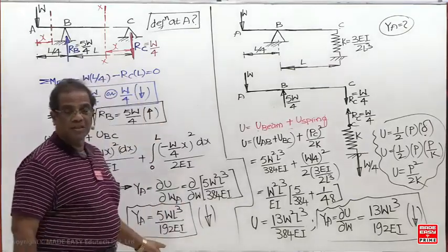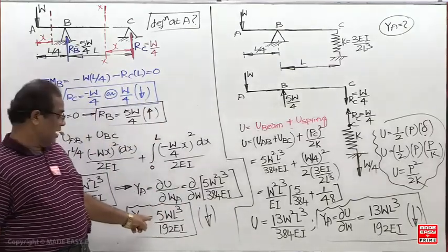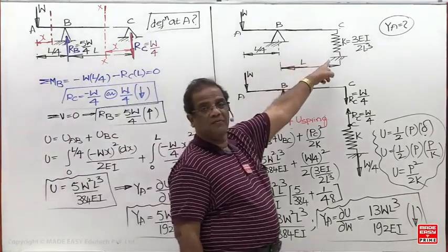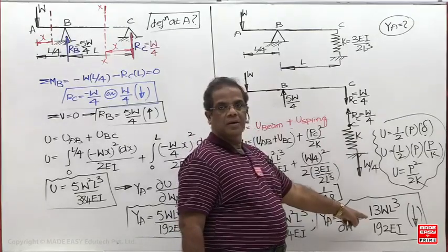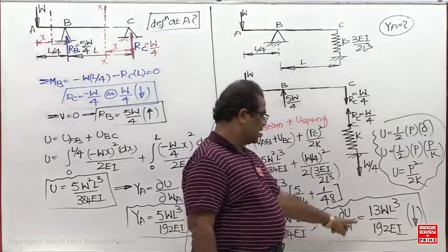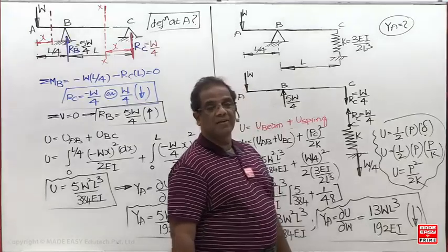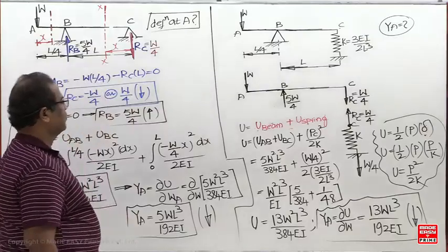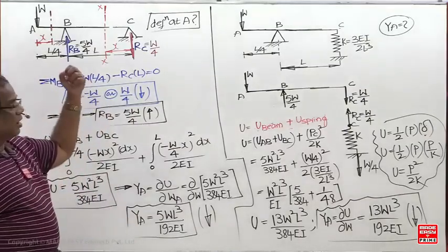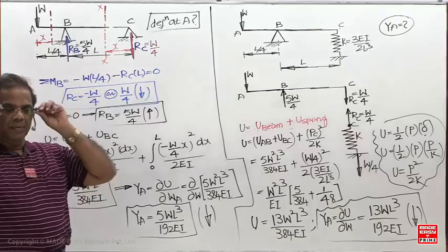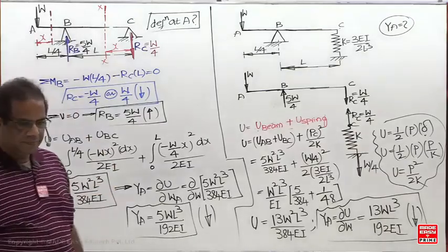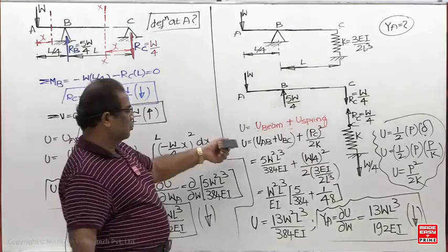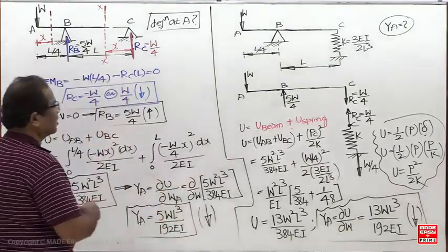Now you can see, when both the rigid supports are there, the deflection is 5 WL³ by 192 EI. Now if I replace one rigid support by a flexible support, so the deflection is what now? 13 WL³ by 192 EI. So for this question, obviously what now? Castigliano theorem is compulsory. This question is directly from the workbook question only. Only numericals are changed now.